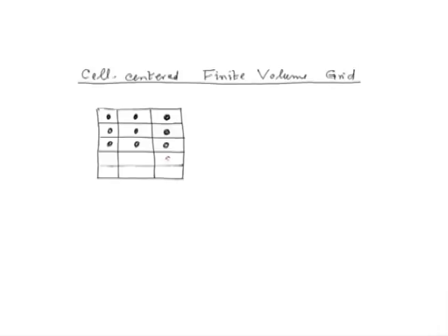So as you can see, this process is fairly simple. It is applicable to not just the structured grid. Suppose we had an unstructured grid over a fairly complex, arbitrary domain, and we had used an unstructured mesh generator to divide it into a collection of non-overlapping finite volumes, which could be triangular, which could be rectangular.